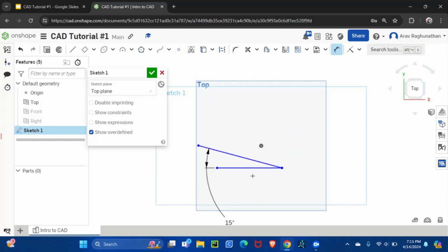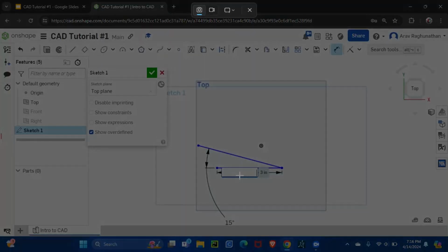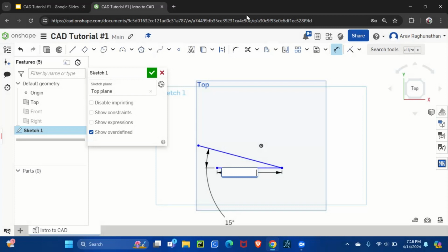So it's really important to understand that on that one it locked this 4 in place and just changed this 3. So when dimensions are created, they are locked in place. Keep that in mind.